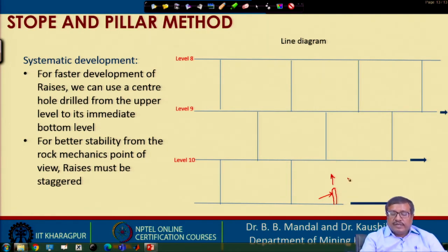So, what are you doing? You are giving compressed air or certain things. Compressed air is the major source of ventilation in raises, and that is insufficient. It is very hot at deeper levels, very hot and humid, and that is why it is not comfortable. It is not safe also. People can fall sick and then cause accidents also.